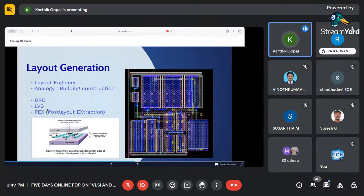So this tool will check whether the layout matches, the connections and the device sizes are matching with the schematic. So if everything is okay, then it is passed. This is called post layout extraction, PEX.